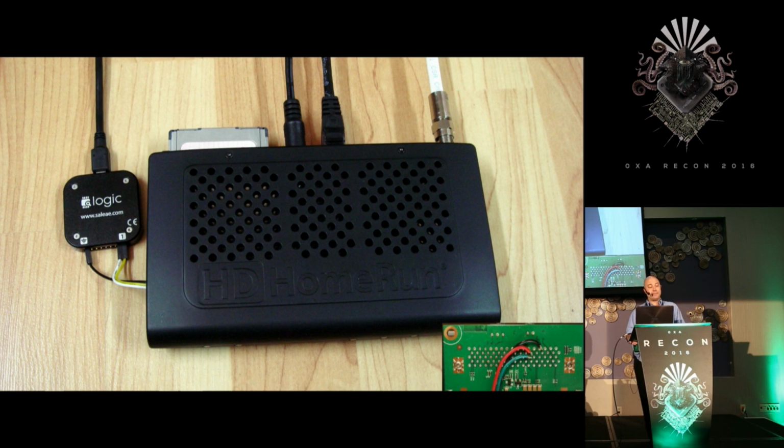Another cable TV adapter is the HD Homerun Prime. It's a network-connected 3-tuner device, and this one has cable card support. The set-top boxes I studied predate cable cards, but newer boxes do use cable cards that support the DC2. With cable card support, that means that the HD Homerun Prime has the tuner and QPSK demodulator to handle the out-of-band channel, so it can pass that data to the cable card. But the HD Homerun doesn't make that out-of-band data available other than via that cable card interface.